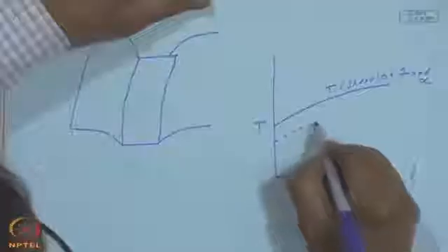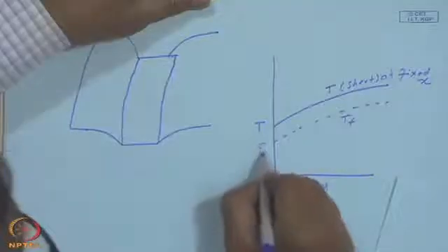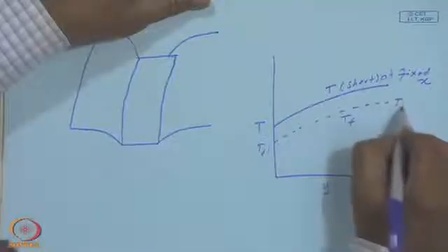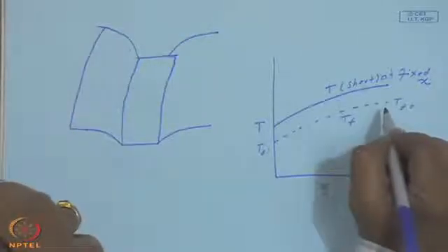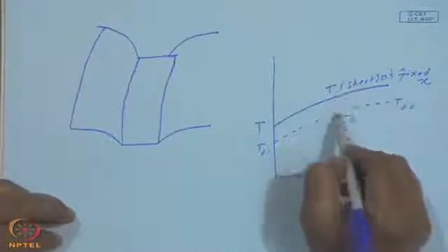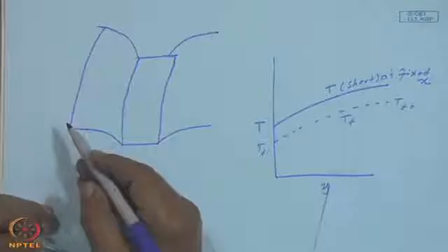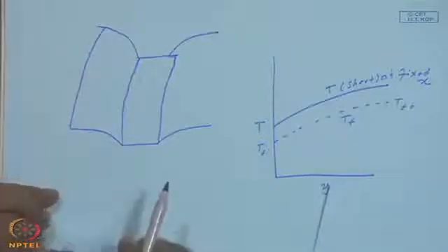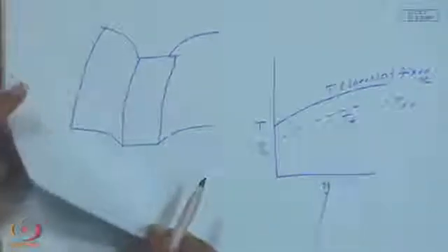Now, this may be Tf, which will be entering at Tfi and exiting at Tfo. So, this is the temperature variation in the y direction at a fixed x, and whether it is high or low depends upon whether it is a fluid region in the tube or the fin region and where we are. And in the x direction, it is maximum at the mid plane of the sheet and uniform temperature across the tube, and again it increases, that element is reproduced.